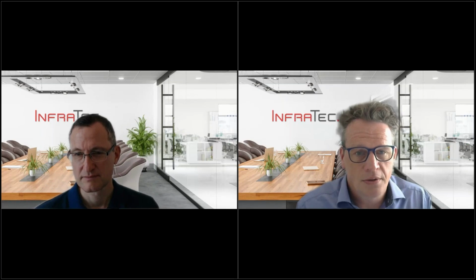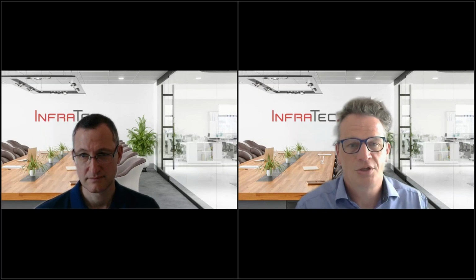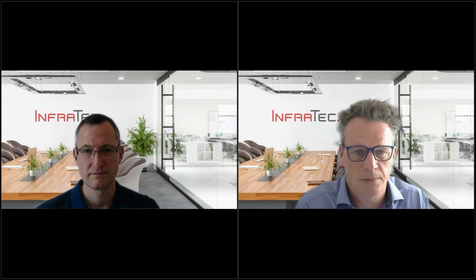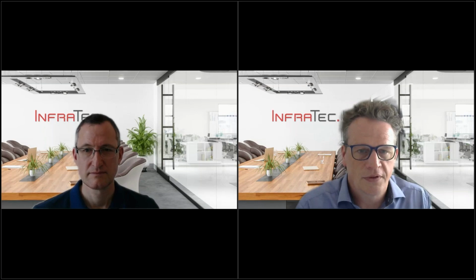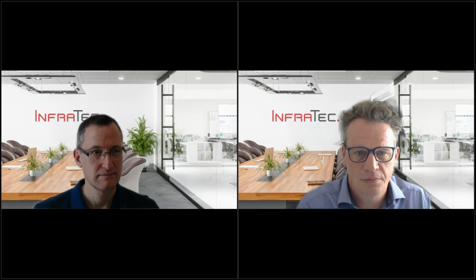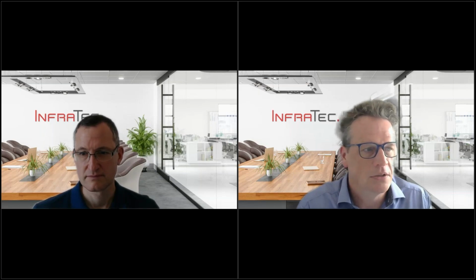To make a picture needs more time, and if you have a very dynamic process, the temperature changes can't be measured as fast as with a photon detector. So we always advise up to a speed of around 50-60 Hertz that it is possible to measure this exactly with a microbolometer, and otherwise we would advise using a photon detector.